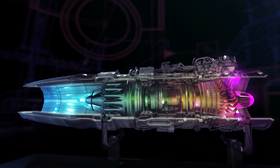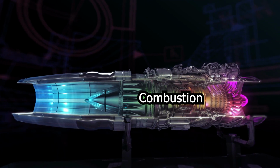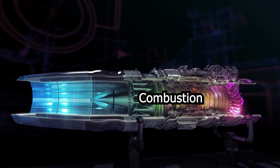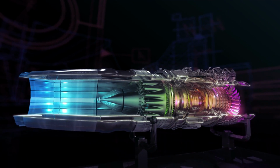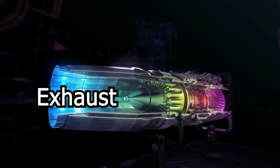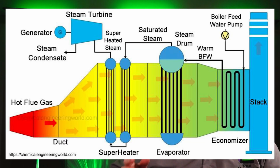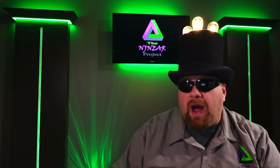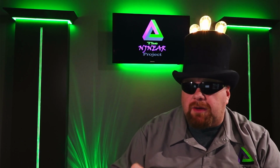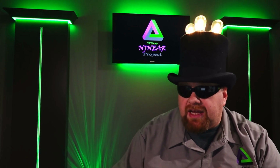Fuel is added midway through the turbine and the air-fuel mixture is ignited and combusted. Once again, the combustion of the air-fuel mixture exerts force against the power side of the turbine fan fins, creating rotational energy similar to the power stroke of the 4-stroke engine, and all the spent air-fuel mixture is exhausted out of the back. In a combined cycle power plant, the exhaust of this turbine would be connected to a heat recovery steam generator. Much like the 4-stroke engine, this engine is losing power to the compressor blades to compress the incoming air. There are quite a few more moving parts, but there are far fewer moving components. Unlike the 4-stroke engine found in automotive vehicles, natural gas turbines provide continuous operation.